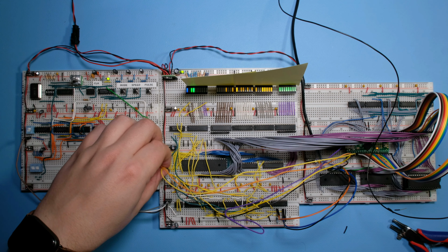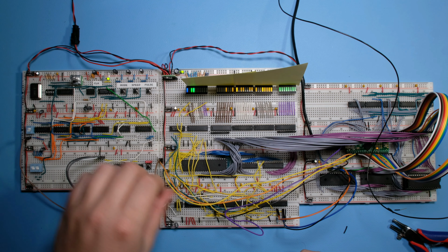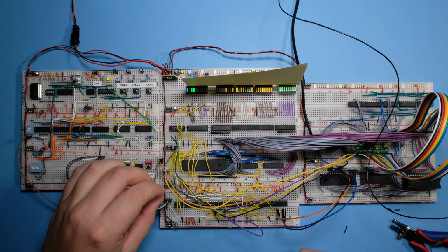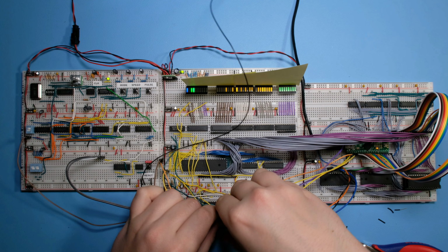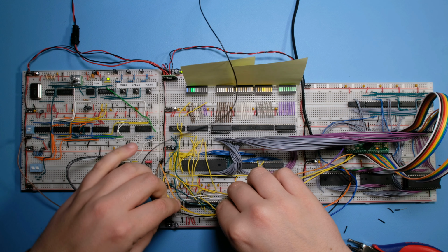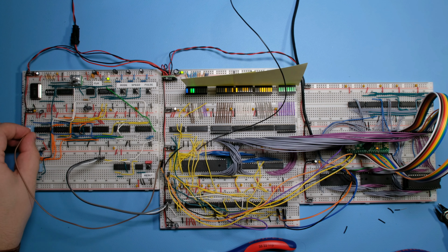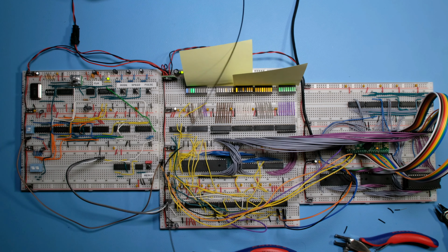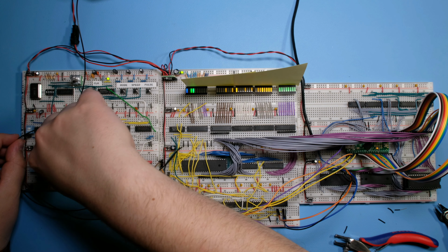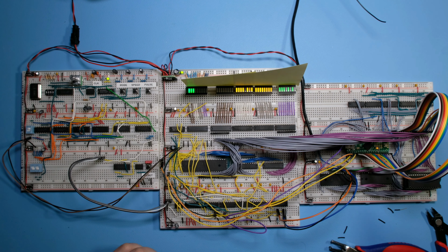Then we have those two. And one is going to the CPU and the other one is going to the clock. And the ground of the CPU is here. So what we can do is use that same ground wire here and have another wire go here to the ground pin at the top here. There we go. And then this one really needs a ground wire as well. And it's gonna be grounded here at the bottom, so I can just go down to ground here. There we go, that's this one.